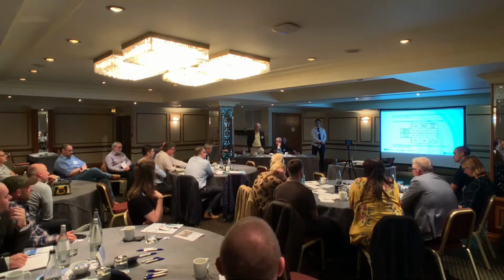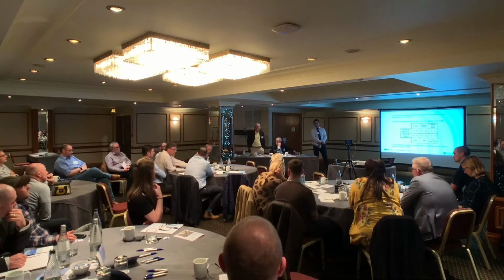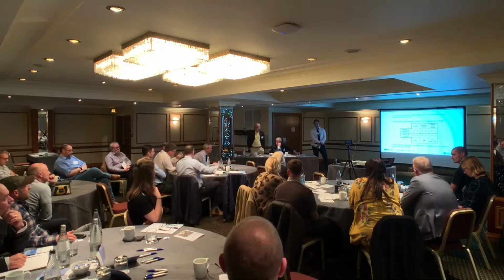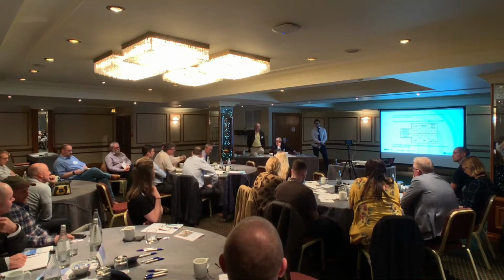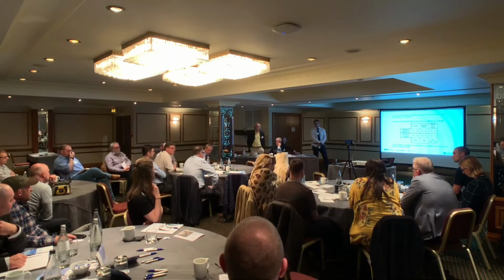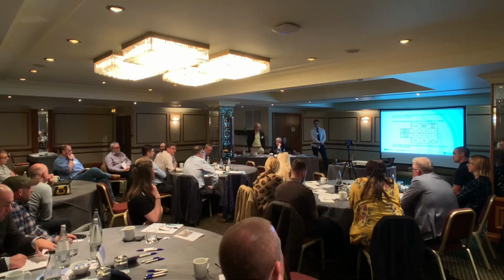I would just add to that, I've seen that before, and it's a bit nonsensical because you can't guarantee that you're making any percentage with it. You can say based on experience, this is what we can deliver, but it's dangerous. I'm not disagreeing. The worst settlement I've seen in London was 3%. That was on the Jubilee line going through Green Park with an open face excavator shield that was 5.5 metres in diameter, and it was tearing the ground. That's the worst I've seen in central London.